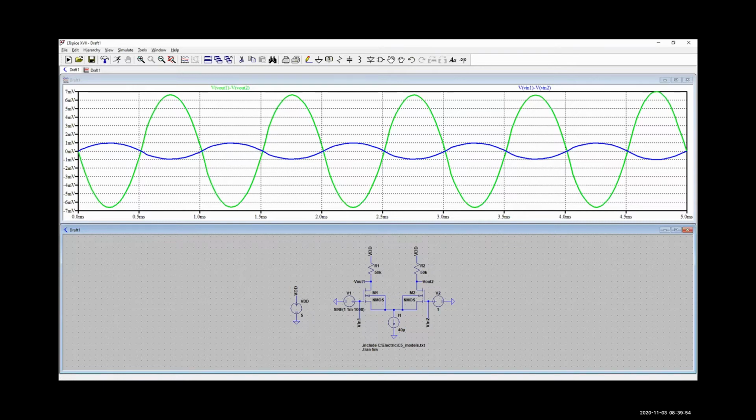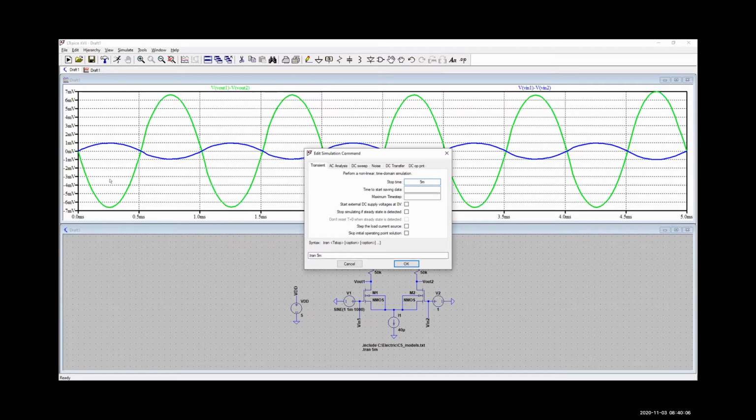And actually, if we look over here at closer to 5 milliseconds, it's actually hitting right on 7. So what I'm going to do is change my simulation command a little bit, because the awkwardness that we might be seeing is potentially due to transient conditions, because we're starting those DC signals up instantaneously.